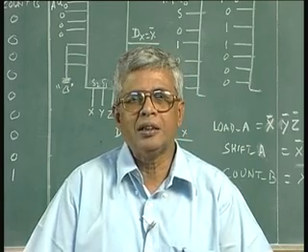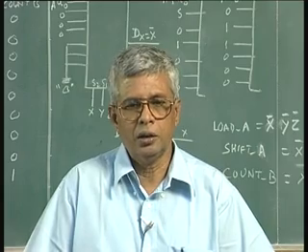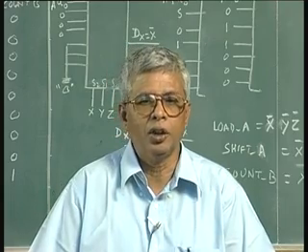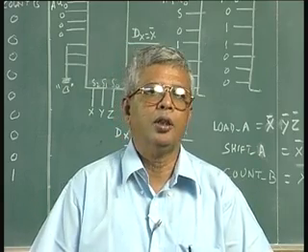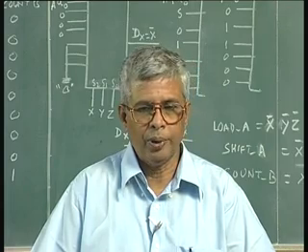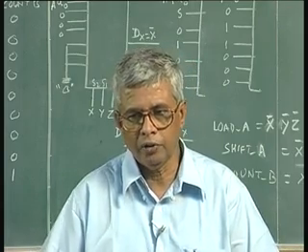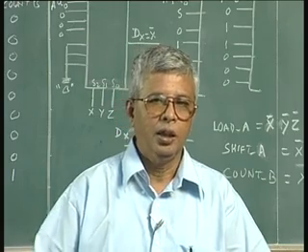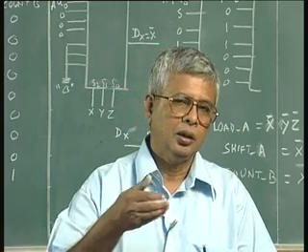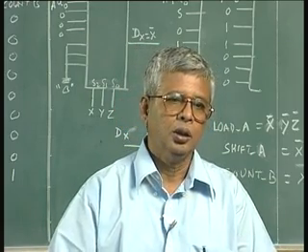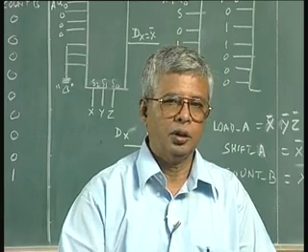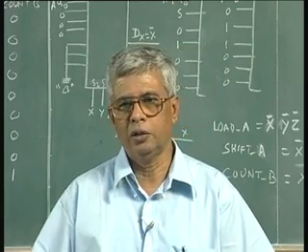Finally, the output will be digital signals, and if digital signals have to drive the analog world, you have to convert them back into analog signals by an operation called digital to analog conversion. So, we have the analog world, analog to digital converter, digital processing, digital output, and digital to analog converter, which converts the signal back to analog in the real world.